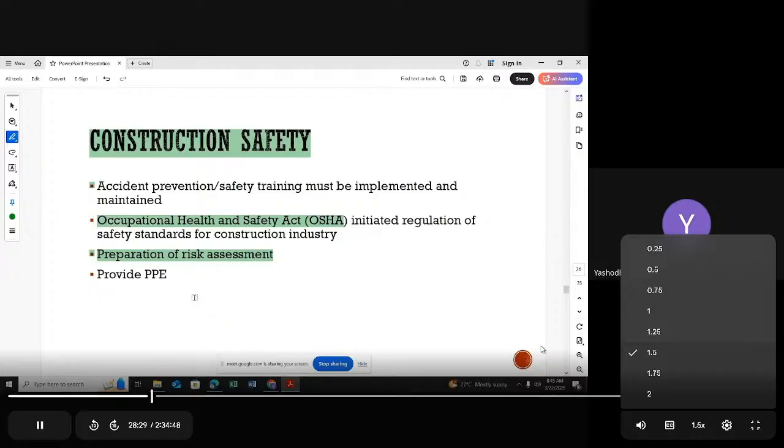Not only that, you all know about scaffolding, which we call palanchi in Sinhala. When staff are working on scaffolding, the safety officer should check all the locks on the scaffolding every day, at certain periods of time, within a few hours. You have seen a lot of scaffolding fixed up high. Checking that the locks are properly fitted is the safety officer's responsibility. Sometimes there is a book near those locks. Sometimes in the morning the safety officer must go and check all the locks and sign. Sometimes after lunch also; they have different time slots. Anyway, the safety officer is responsible for that, going and checking the locks.